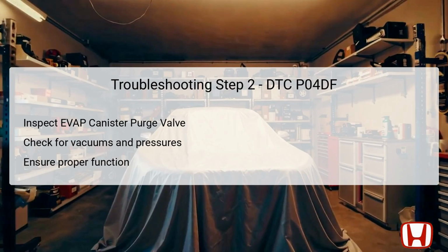It's critical to apply vacuum or pressure to the appropriate ports of the valve to determine if it opens and closes as required. Any deviation from the expected behavior can confirm that the purge valve is either stuck open or closed, which would result in the conditions triggering the DTC P04DF. Inspections should follow manufacturer specifications outlined in the service manual, ensuring accurate and reliable diagnostics.